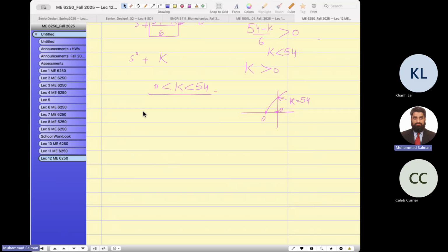One more thing you can write down here is the angle of departure and angle of arrival. So the angle of departure is 180 plus the angle of GH. The angle of arrival is 180 degrees minus the angle of GH. For example, if you have poles located here inside the plane, at which angle do you leave? You will use this formula to see what the angle is. Suppose this is the angle of departure here.